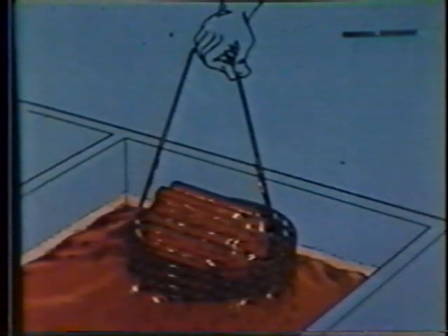Removal of post-emulsified penetrants begins with application of emulsifier. Best control is obtained by dipping. Brushing or wiping is not recommended. Emulsifier, on application, immediately begins diffusing into the penetrant. Action stops when water is applied. The duration or length of emulsification is critical. Too little time and surface penetrant may not be completely removed. Too much time and the penetrant in discontinuities becomes water washable.